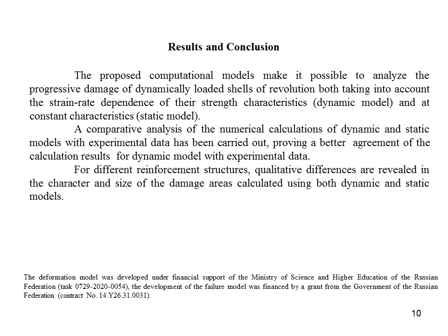The proposed computational model makes it possible to analyze the progressive damage of dynamically loaded shells of revolution, both taking into account the strain rate dependence of their strain characteristics, dynamic model, and at constant characteristics, static model. A comparative analysis of the numerical calculations of dynamic and static models with experimental data has been carried out, which shows that the calculation results for dynamic model are in better agreement with experimental data. For different shell reinforcement structures, qualitative differences in the character and size of failure zones were found, which were calculated using both dynamic and static models.